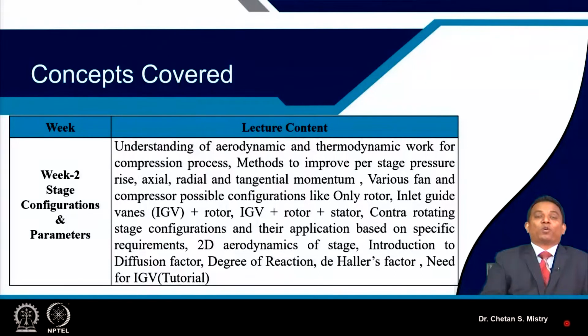Then we were discussing the different configurations which are possible for our axial flow compressors and fans. We have considered the special applications where we are using a single rotor, or only rotor with inlet guide vanes, and rotor configuration. We have discussed the rotor and stator configuration. We have discussed the inlet guide vane, rotor and outlet guide vane configuration, and as we have discussed, that's what we call the 1.5 stage configuration.